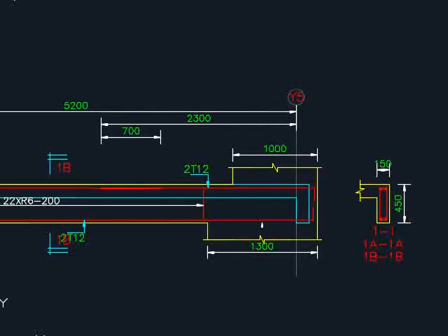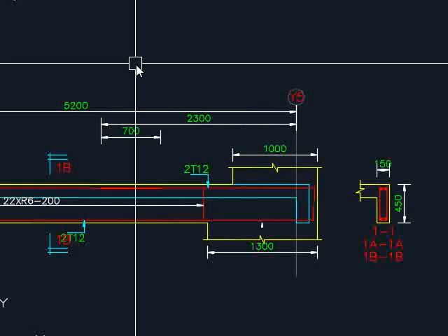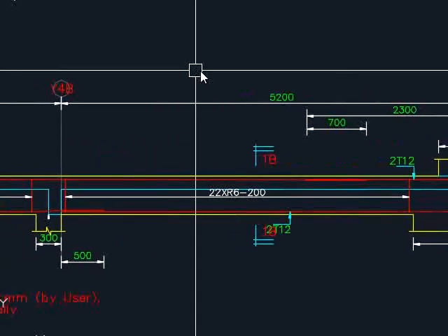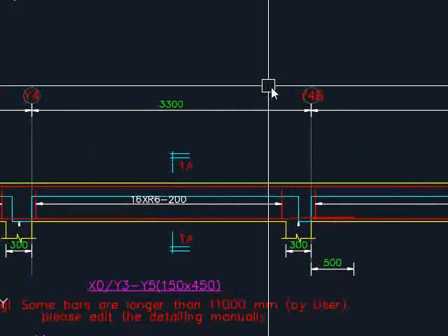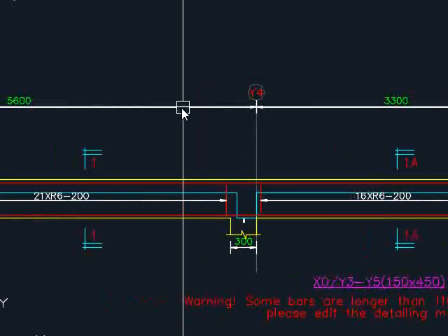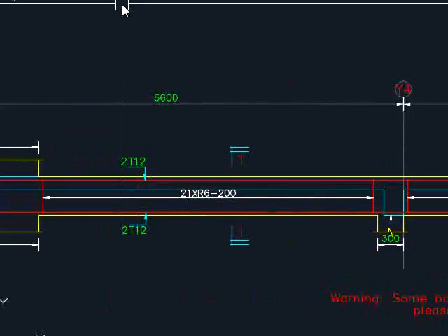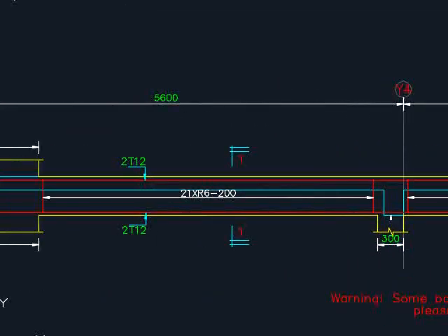However, for friendly usage, you might need to simplify further, remove certain unnecessary lines or information which may not seem to be as essential to the contractor, especially when you talk about the detailings of the beam. You are more concerned with the reinforcement bar. How many reinforcement bars are required? Where should they be located? Where are the lapping lengths?